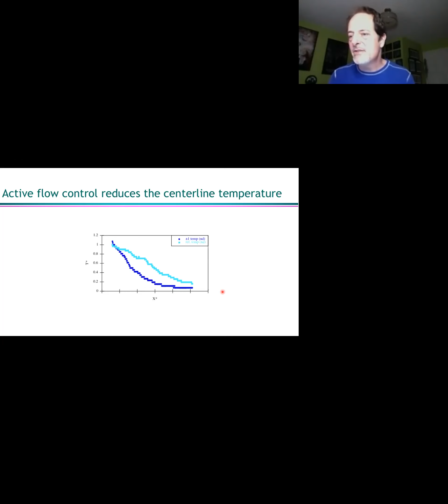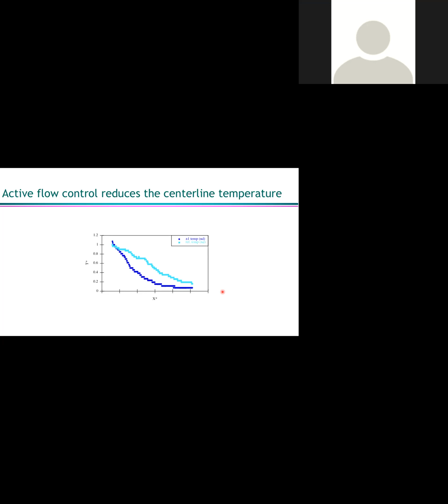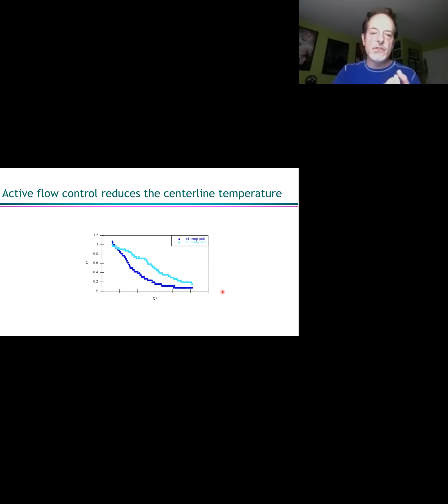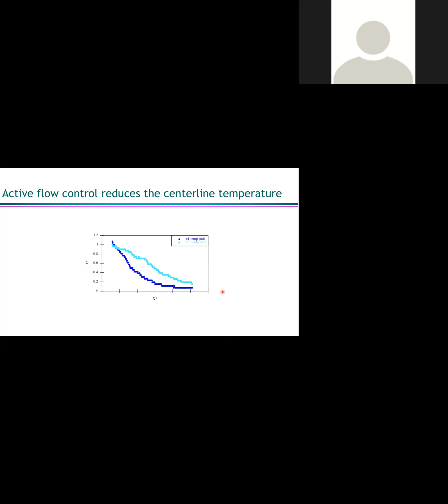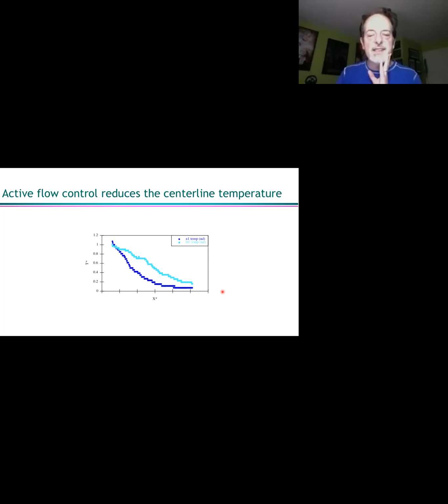I guess to put it into something that I'm sure you're familiar with, and probably other people are, they put riblets on airplane wings, right? And what that does is it's passive flow control. It introduces three-dimensional vortices to help keep the flow attached to the wing. So this is more like that. So it's like a stall kit sort of. I get it. Okay. All right.